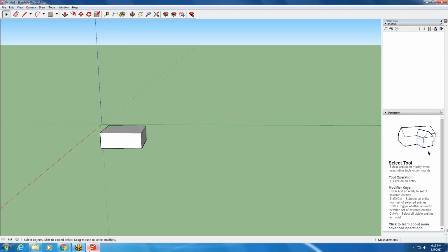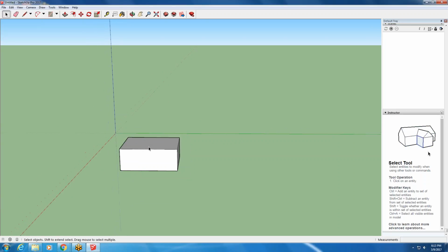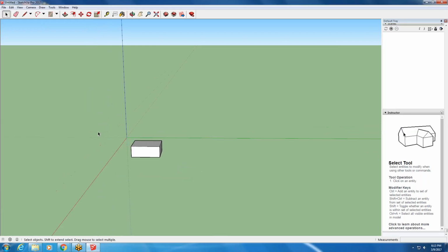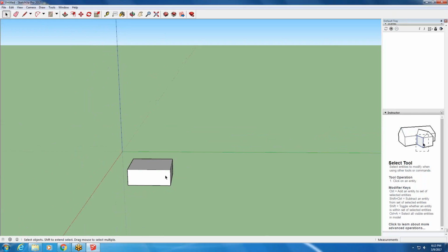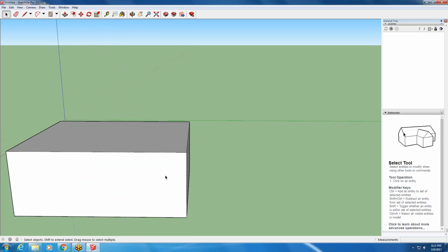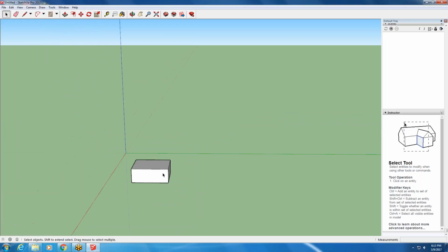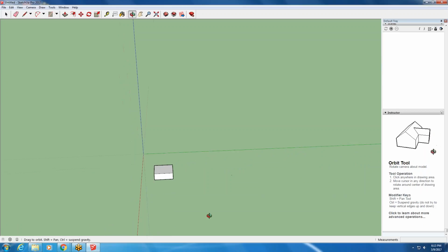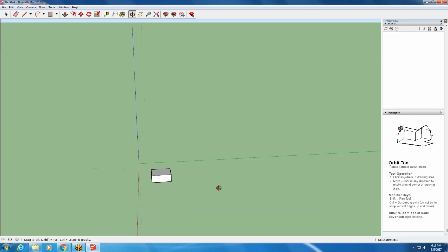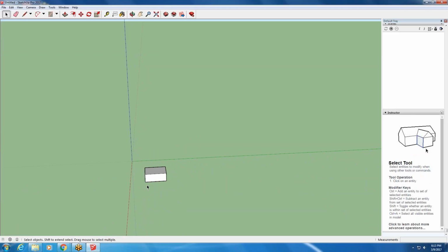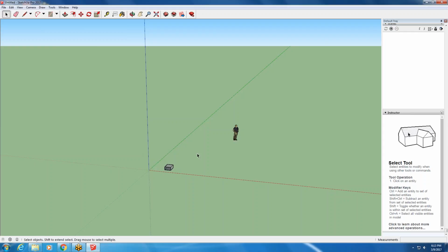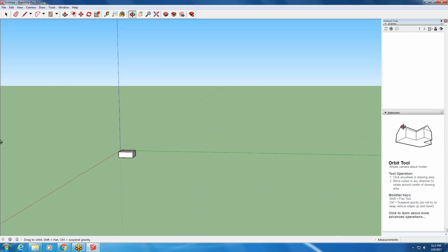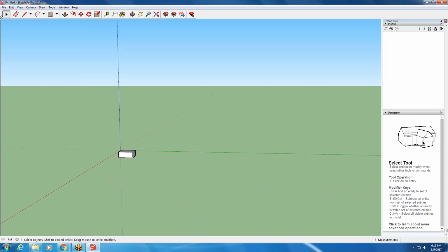If you want to have 2 SketchUp files at once, this is where the clicky mouse comes in. So just like having a scroll mouse for AutoCAD is very necessary, it's just as useful in SketchUp. It's allowing me with my scroll at the center of my mouse to zoom in and out really quickly. I can press down the scroll to pan in and around. And then if I click to one side or zoom out at the same time, it's a pretty useful tool. I could do all of those things up here as well.